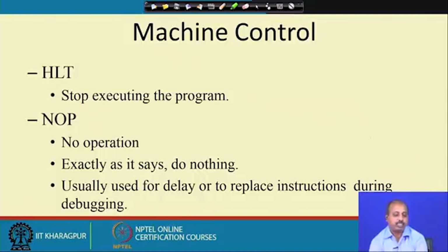And there is a no operation. Another very interesting instruction that we have is the NOP. That stands for no operation. So, what does it do? It does not do anything. It is used mainly for delay. If you want to put some small delay, you can put this NOP instruction, and many times for program debugging this NOP becomes useful.